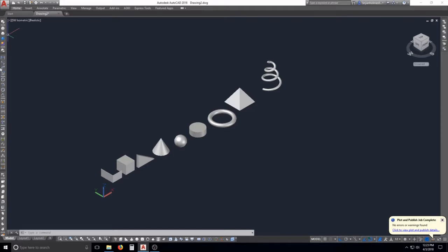Now we're going to get into some of these other tabs in a little bit, for instance your dimension tab. That's a pretty important one in 3D modeling. It helps you move things without getting them thrown way out in space, even though you think you're drawing in the same XYZ plane. Sometimes you're not. In theory you could be drawing 600 feet into the drawing and not realize it.